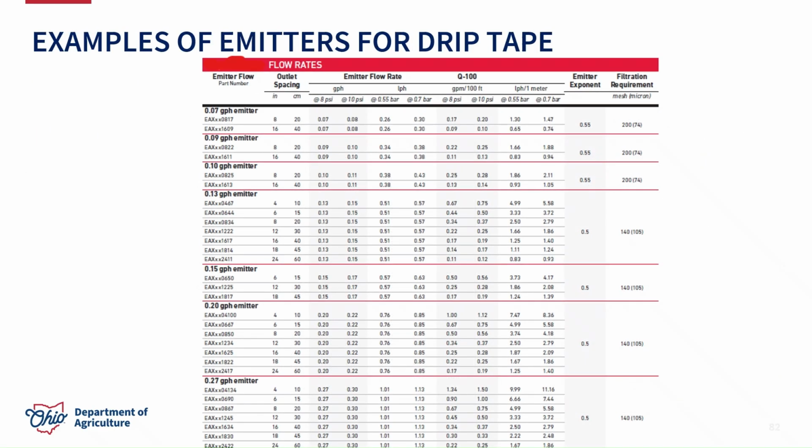At some stage along our microirrigation design, we're going to need to select the emitters and the laterals that we're going to be using in design. It's always good to contact the producer and understand if they're already working with a local irrigation company or supplier, or if they're frequently using a different type of tape. They may oftentimes not know what tape they want to select or where to go. And at that stage, right, we have a little bit more flexibility of sizing and selecting probably the most appropriate size tape for their application.